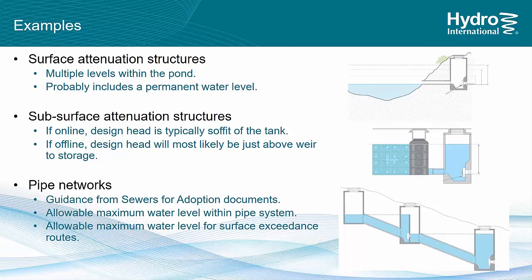And with pipe networks, again, Sewers for Adoption goes into a number of those points discussing how much water you can hold in pipework. But again, oversizing pipework around the catchment and what the cover levels might be will then end up determining what head levels are available to you.